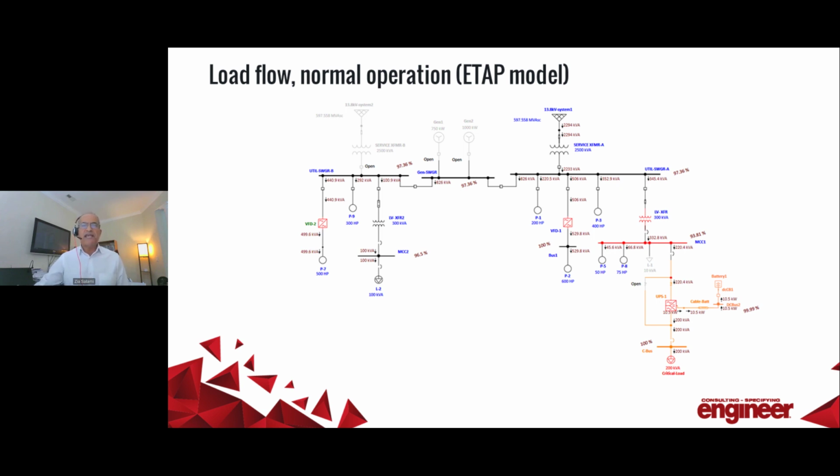Normal operation in this case means that the power is going through the UPS, the inverter, and supplying the load. At the same time, we are charging the battery. Keep in mind that when sizing is involved, we need to consider not only the amount of the load that we need to supply, we also need to pay attention to the amount of power required to charge the battery at the same time.